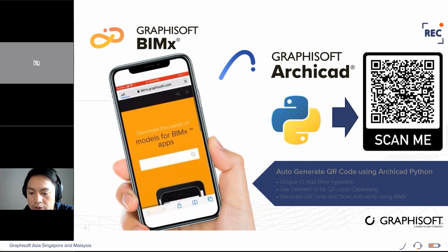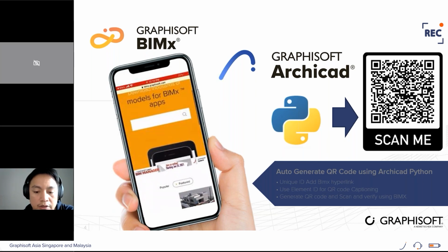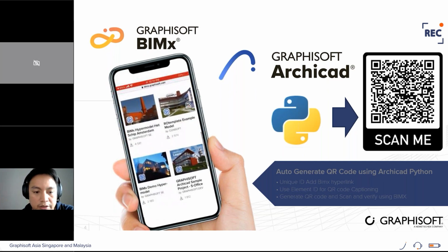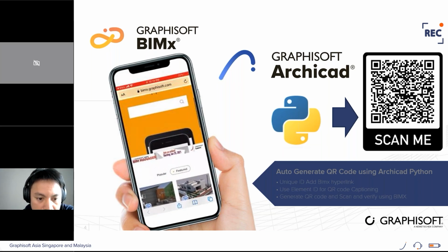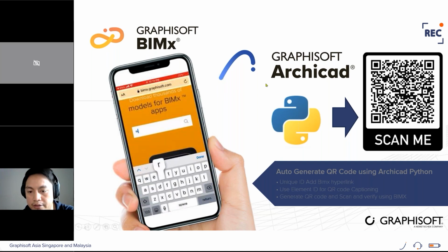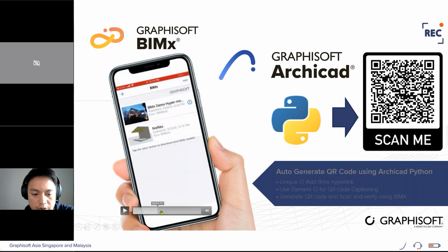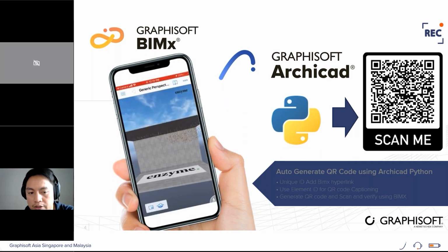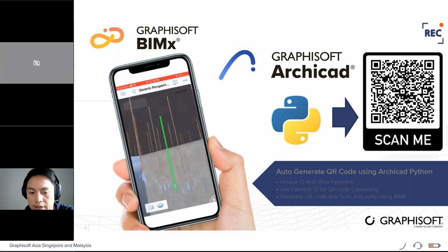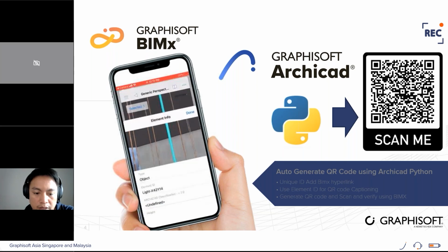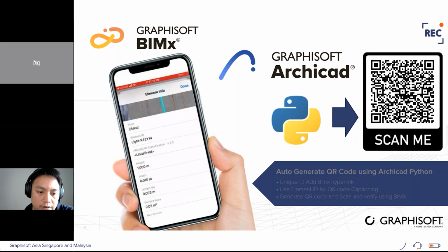Let me show you what we have done so far in the previous session. Basically, we auto-generate QR codes using Python based on the element ID. Then what we did here is scan the QR code with your phone, and it will verify the location inside the BIMx application. Let me fast forward a little bit so that you can see the progress. As you can see here, we generate all the QR codes. Then the BIMx app will automatically pop out and give you a notification to open it. As you can see here, it opens and locates the element.